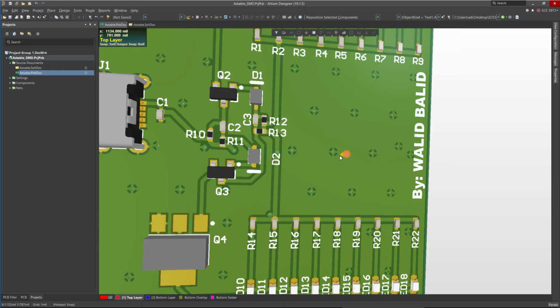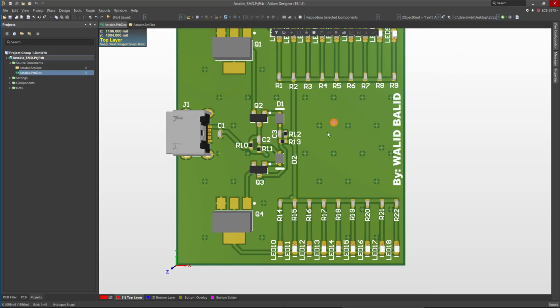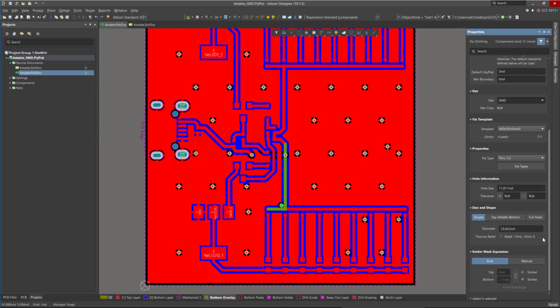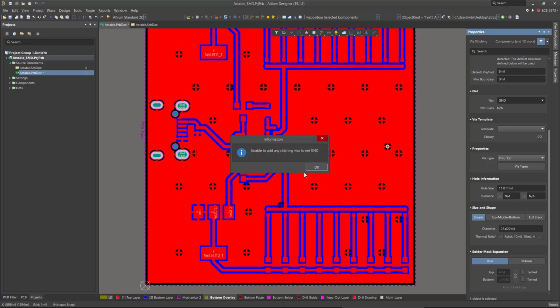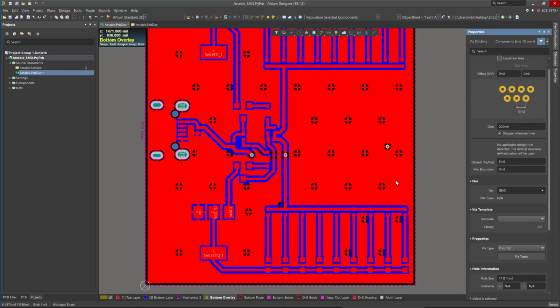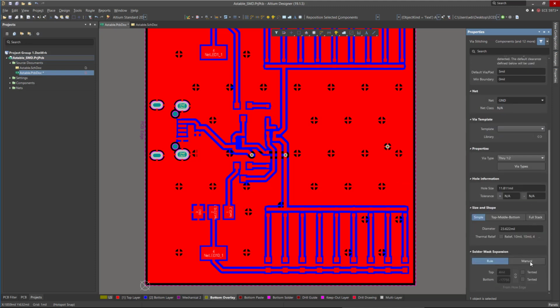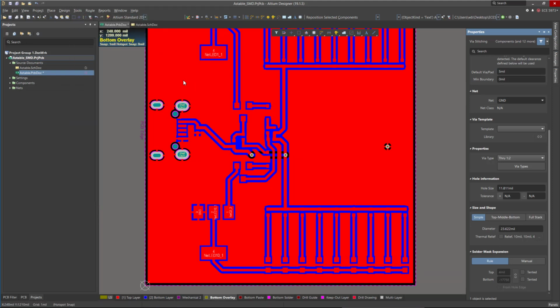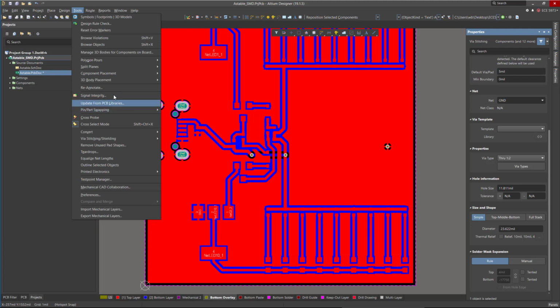Okay, so they are tinted. You barely can see those vias. So let's change these vias now into not tinted vias. Oh, for some reason Altium Designer is removing these vias. But let's choose Polygon Pour, Repour All. Let's add these vias back.